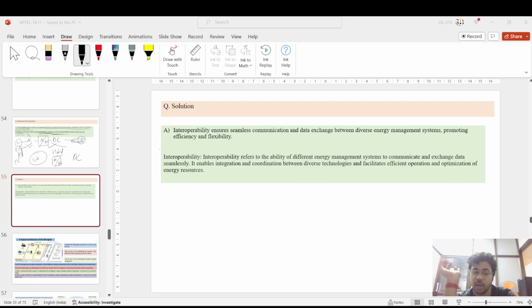In that situation also the discom is controlling everything. Above SLDC is CLDC, and those SLDC have the power to manage and curtail during load shedding, between demand and generation mismanagement.